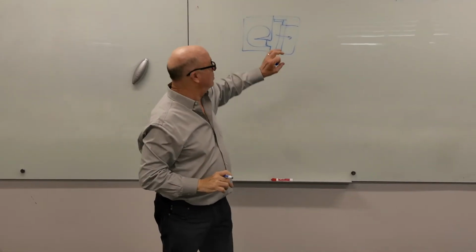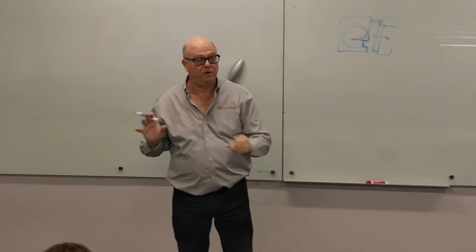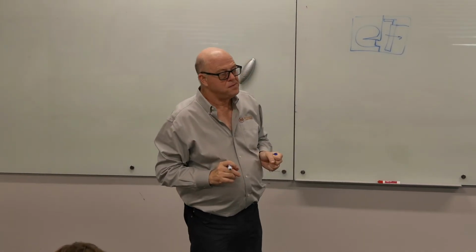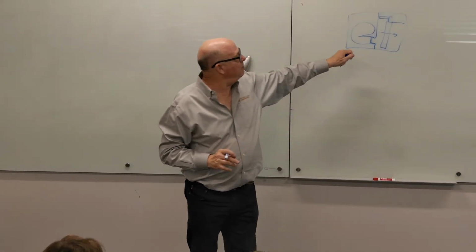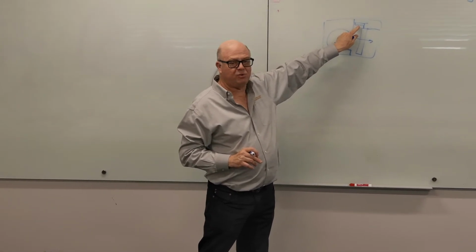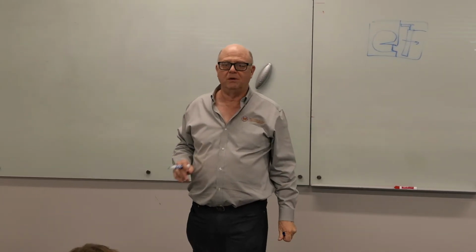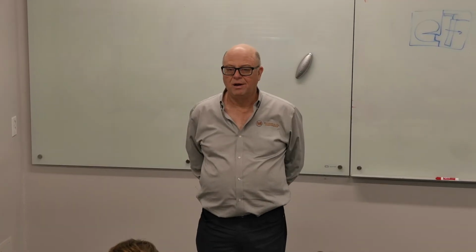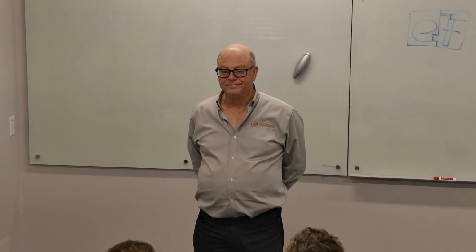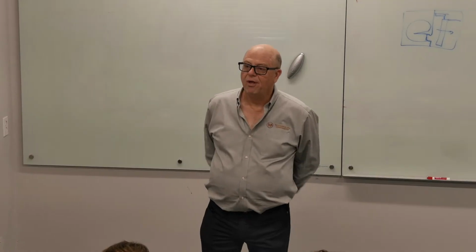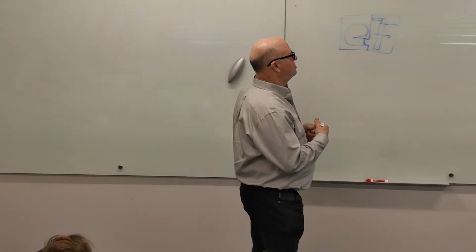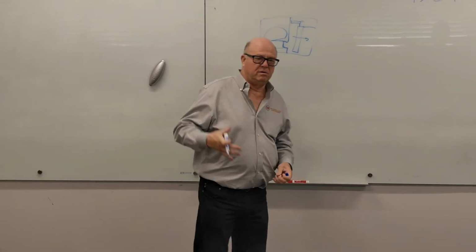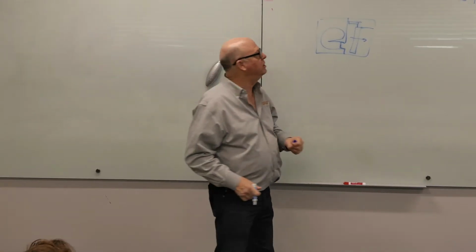So no, this is not reheat. That's an important point. First step is, why is that heating coil so much smaller than the cooling coil? There's 2 reasons. Less delta T. Less delta T is the reason, but then that leads to some things.